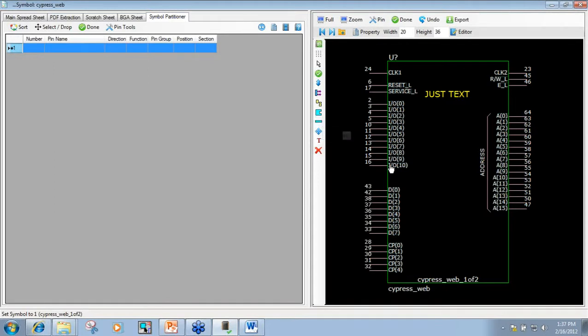We can also do things like, some people have the requirement to create IEEE logic symbols where you might have a cutout in a part. So you could do that. You could put the cutout with a line across to segregate your chip into functional blocks if you wanted to. All right, so that's kind of the symbol creation.